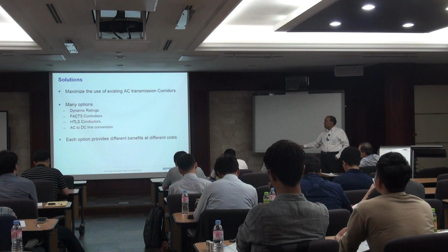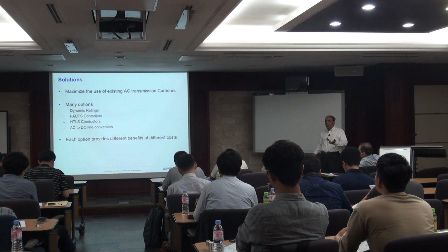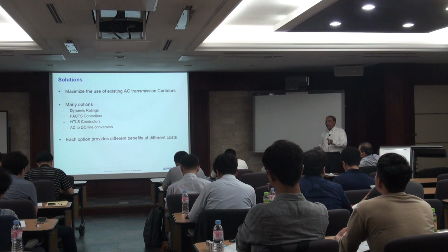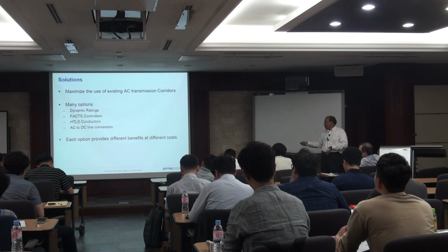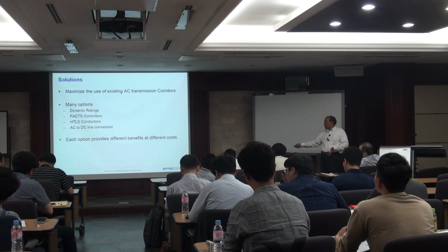FACTS controllers are power electronics based controllers. They can also change the phase angle difference, change the impedance in the line, or increase the voltage at the bus close to 1 per unit. They can also change power flow, maybe by 30 to 50%. So if you install FACTS controllers, you could do that.